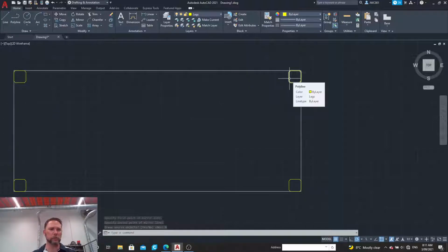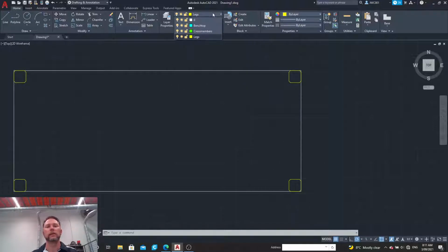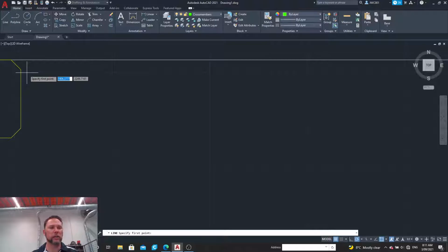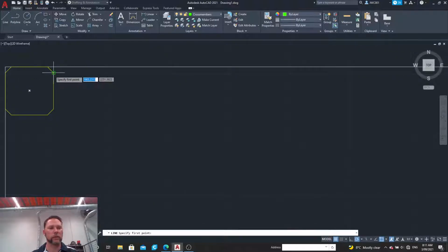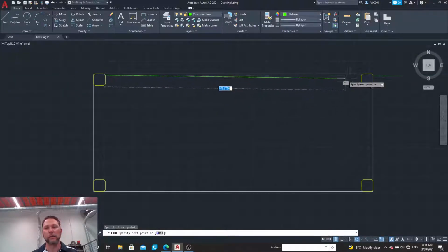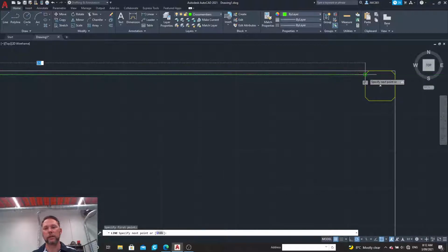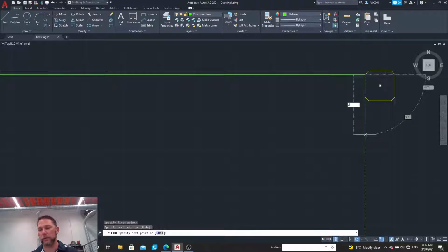All right, now it's time to draw my framework going between my legs. So I'm now going to select cross members. Why is this mouse not working? All right, and I'm going to draw a line. Now I'm going to start on this edge here. I guess I could start at the middle, but I actually want to start here. I'm going to run that all the way across to here. I'm using 20mm Jarrah, so I type 20, enter.